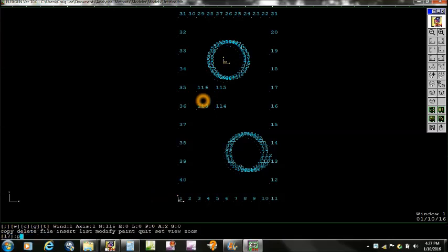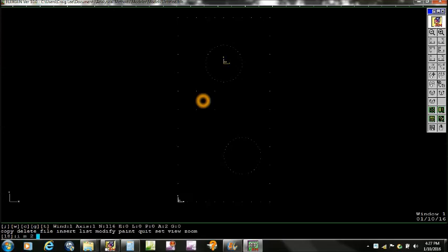And we'll set the node labels off. And now we want to insert the mesh. So we have all the outline done, the circle, the square. We want to insert the element mesh. So we're going to use plate 3s, which are triangles.